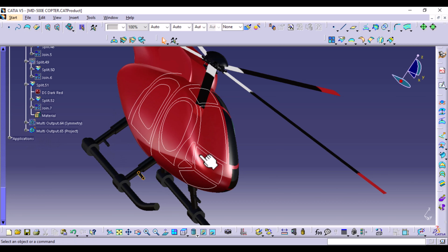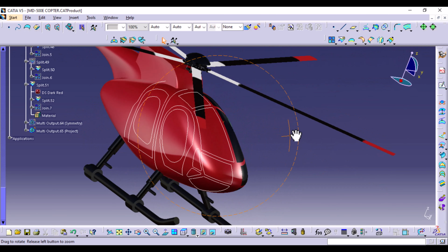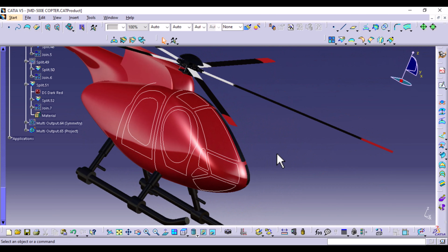And now these are the ones you're going to use to create the same surfaces we did on the other side. So a tubing here, but now remember, you're going to use the radial curve. You're not going to create another parallel curve when you're creating the tubings because we have selected the one in the middle now. This is the one in the middle. And then this one we have 2 gaps and you close on the other end. I'm not going to repeat. I've just shown you the curves. So I'll just skip ahead to where I've already done everything that is supposed to be done.